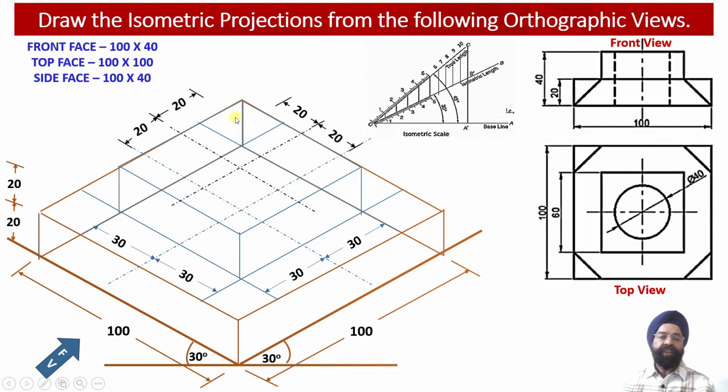Now with respect to these two center lines, we are going to draw 2 projector lines on either side of these two center lines, such that we obtain a square projection corresponding to this center of symmetry line. One projector line we have drawn on the left hand side of this particular projector at a distance of 20 millimeter. Another projector line with black color we have marked onto the right hand side of this center line. So this distance will be equal to 40 millimeter.